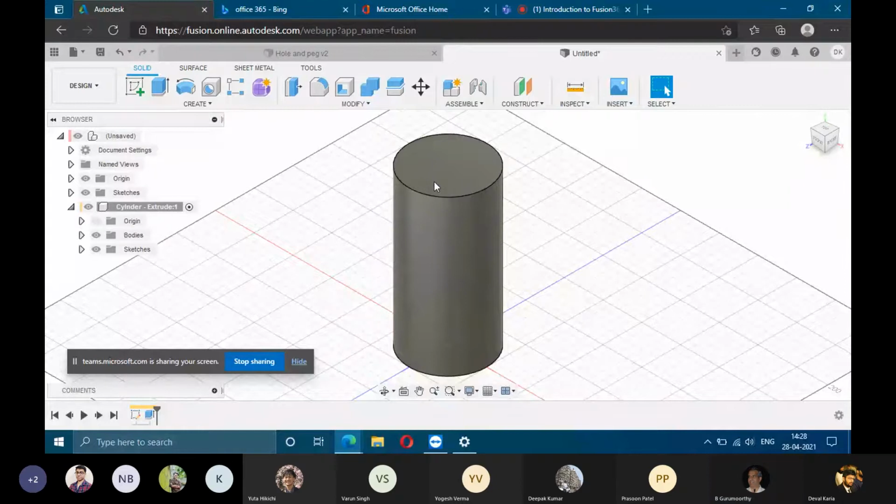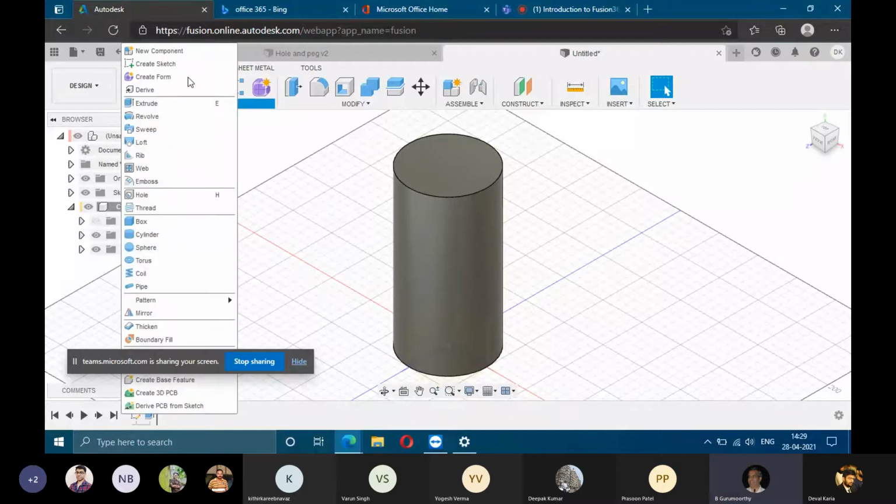As you would know from basic geometry, this is the axis of the cylinder. Now there's another way I can create the cylinder, which is to take a cross section of this cylinder, take half of it, and then revolve it around the axis of the cylinder, right? So this command will help you create any axisymmetric component. Let me do that by creating another component.